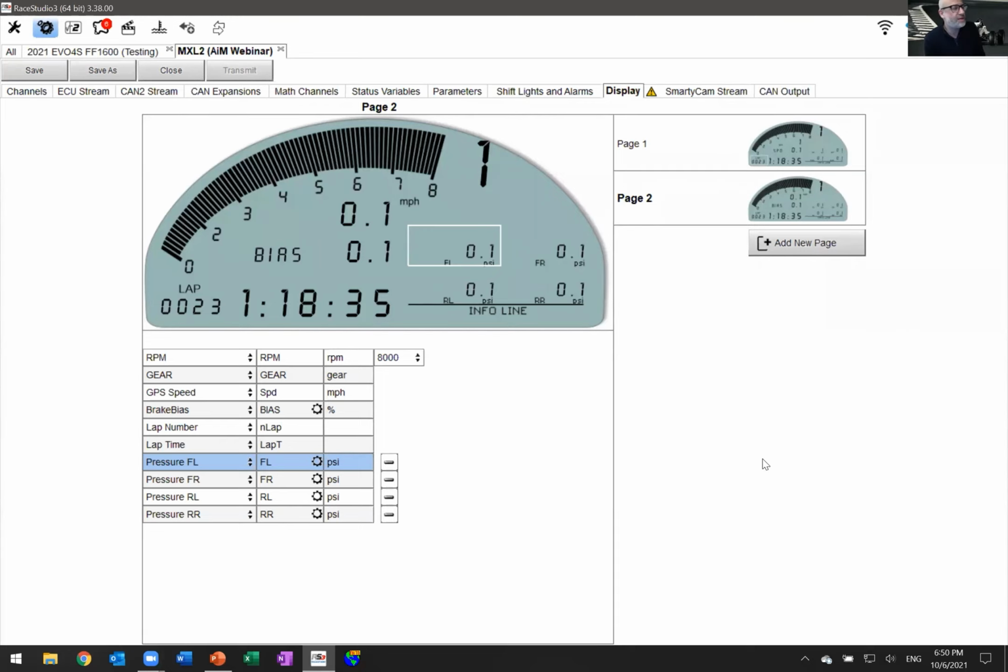Some of the advice that I would give to anyone who's setting up any of the dashes, alarms, anything that's on screen: only ever show information to a driver which is critical that they do something while they're on track, unless, of course, you're testing. But generally speaking, if you're in a race, do not fill the driver's attention with alarms or alerts which don't have a material or significant impact on their driving performance while they're racing, because you don't want to distract people.